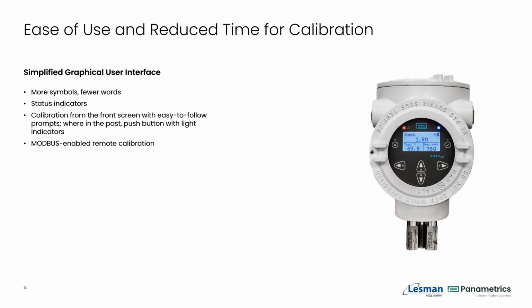Our recommendation is when you first get the transmitter, calibrate it out of the box, or at least put the cal gases on the transmitter out of the box, and make sure that everything is working properly. More often than not, assuming that you haven't had this sitting in a box somewhere for months and months, you probably have to make no adjustments right out of the box. My recommendation after that is do your first cal, or at least a verification, 3 months down the road. And then again 3 months after that. That'll give you an indication as to how stable that calibration is in your application. After that, you'll get a sense of whether it should be every 3 months, 6 months, or yearly.